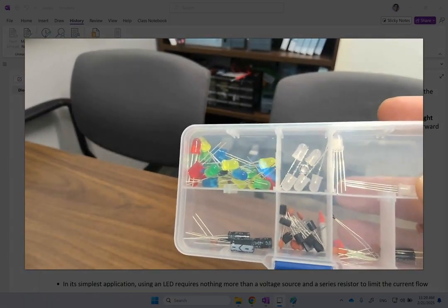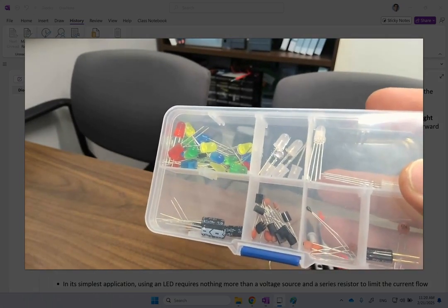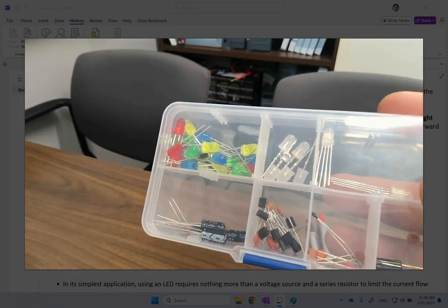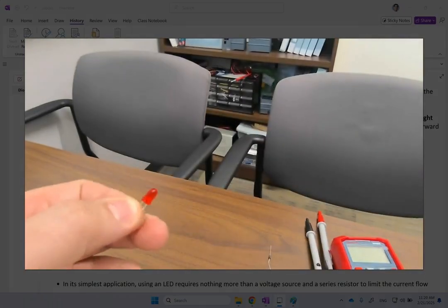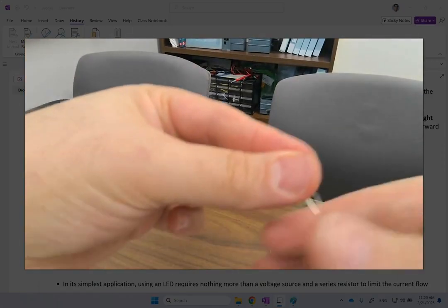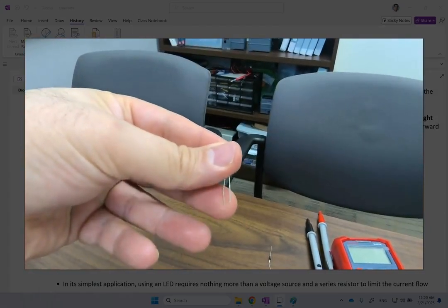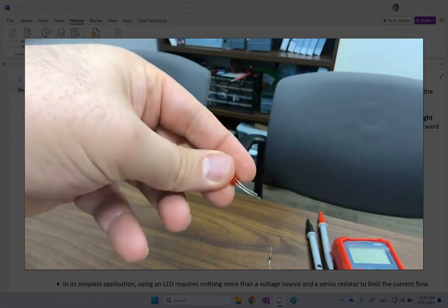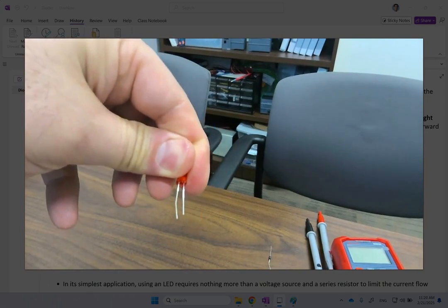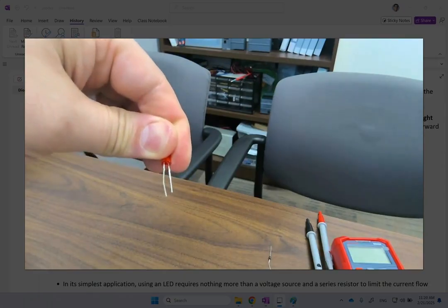I made a video on them on a separate occasion, I guess a week ago or so. These are called RGB LEDs, so they can literally create any color that you want by passing them R, G, and B values. Okay, so there are all sorts of LEDs, and if you look at them, they have two legs, and one of the legs is taller than the other one. Let me go back. You can see here, this one, the left leg is clearly bigger than the right leg, to indicate which one is anode, which one is cathode. One leg is longer, and these guys will emit light.